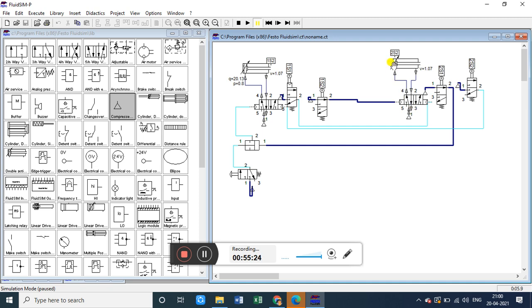Yes, air will come out from this valve and go inside the cylinder from the left side line, and because of this the piston has to move to the right hand side. But right now we are going stepwise, so it has not started its journey. The right side air will come out, but later. Before starting this movement, 2s1 is in pressed condition and 2s2 is in unpressed condition, but over here 1s2 is in pressed condition after the cylinder's extension.